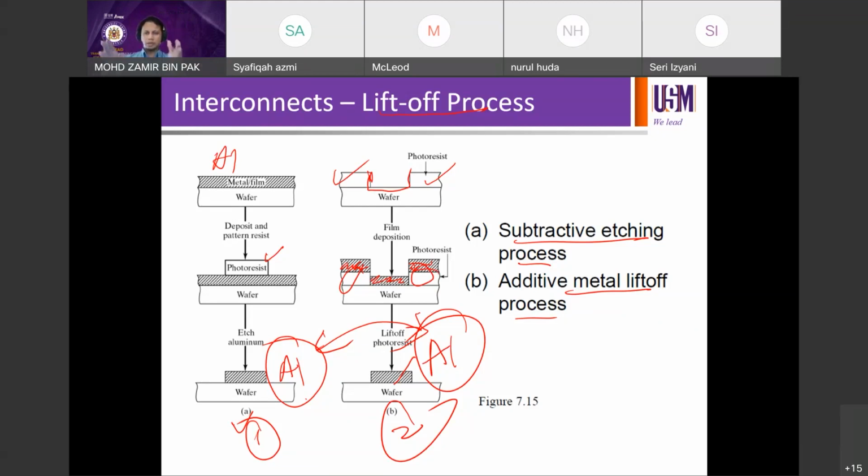You do the process for 200 nanometer, for example, and then you come back after etch. You come back in the next cycle, and then you don't have to coat the resist, but you just etch. You just expose the existing pattern with 200 nanometer halfway, so that you can develop halfway, and then you are left with the 100 nanometer with remaining polysilicon. So those are the examples of how you can approach fabrication from different angles. The same goes for this lift-off process.